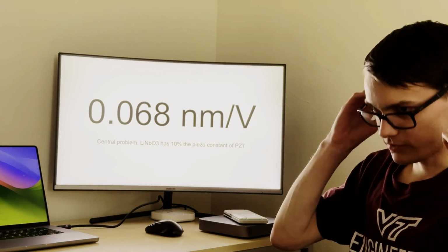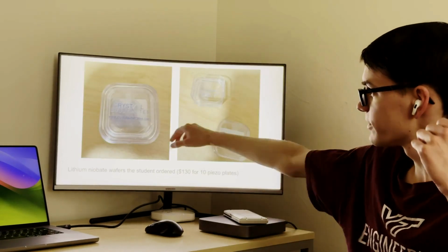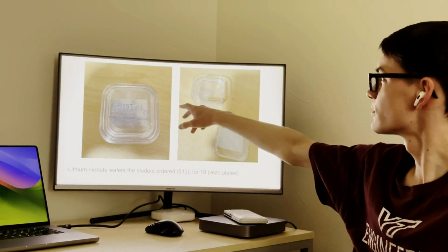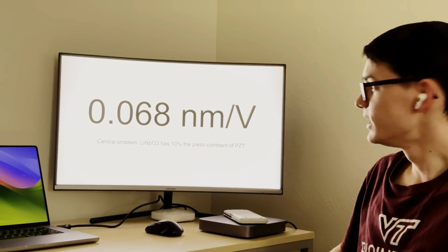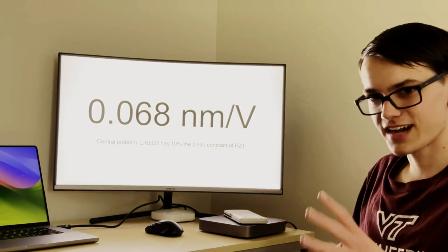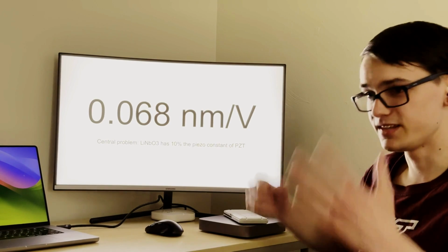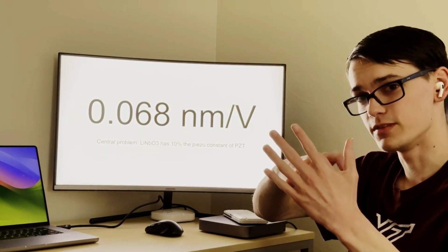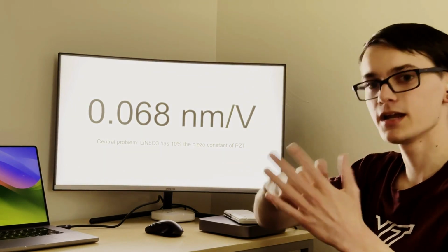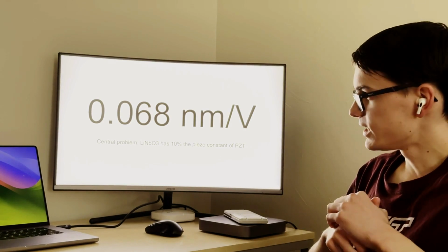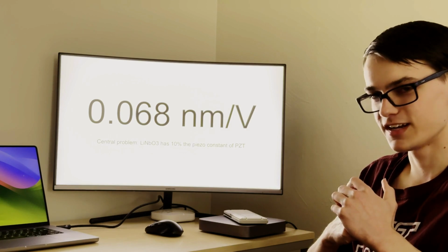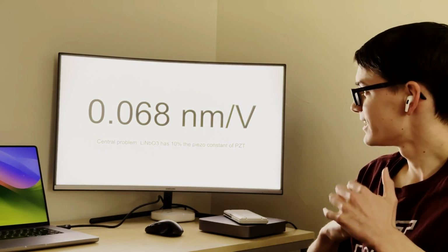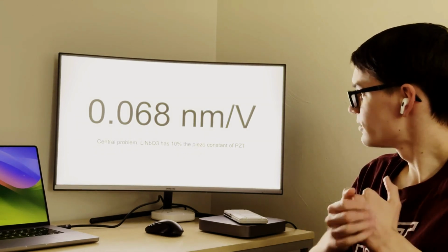And when you try doing that with only 10 piezo plates, remember I was going to do the entire semester with only these things, you need very, very high voltages, and you need like three different stacks to get a kinematic mount to approach the tip to the surface before you even do the scanning. And I got hit with trying to explore the design space of control electronics with this kind of constraint, and I kept running into issues.